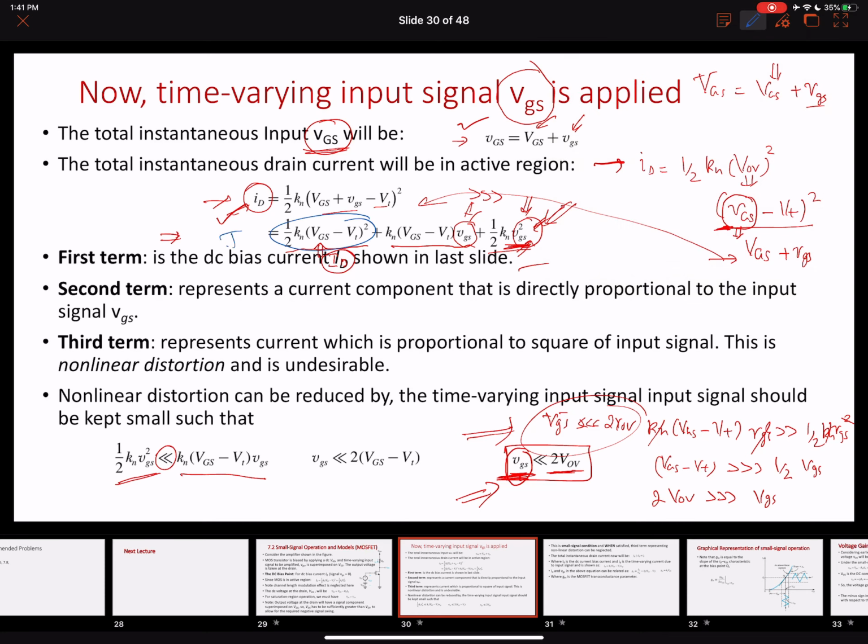Please note that over here there is no inversion. As you increase the gate to source voltage, your drain current increases, because you can see from this plot that it's a direct relationship rather than an inverse relationship. And this gain, the ratio of the change in id to the change in vgs, is equal to the slope. We have seen that id over vgs is equal to gm. So gm, the transconductance parameter, represents the slope value as well. This can also be rewritten by taking partial derivatives of this.